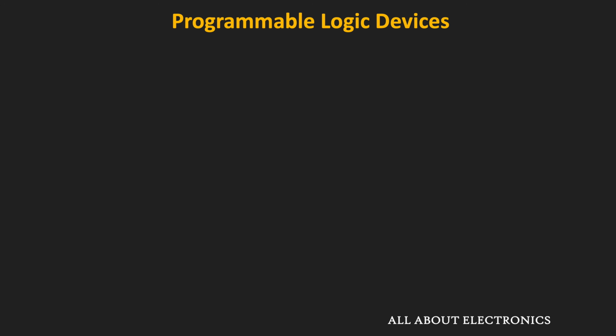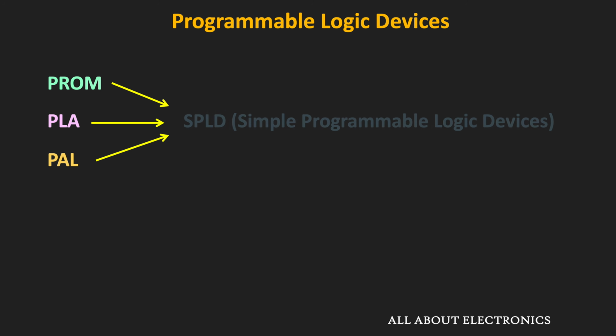So in the last couple of videos, we covered the PROM, PLA as well as the PAL. And if you see all these three programmable logic devices, then they are known as the SPLD, that is the simple programmable logic devices. And using these SPLDs, it is possible to implement various logic designs.